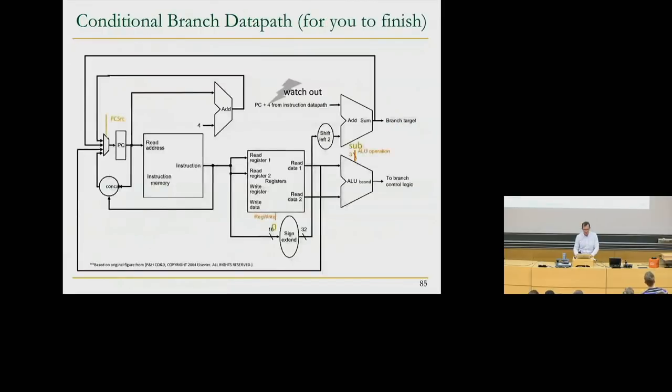So we need to be able to do this. I'm not going to give you this in this slide. First of all, whenever you implement this, you should ensure that you don't do any harm. This doesn't write into any register or write to memory. That's why memory is omitted over here. To be able to implement this, you need to add more data path elements so that you can subtract the source register from the destination register, and then you get a value. Then you need to compare if that value is equal to 0. So there's some logic that needs to be added. If that value is equal to 0, then you take the target address.